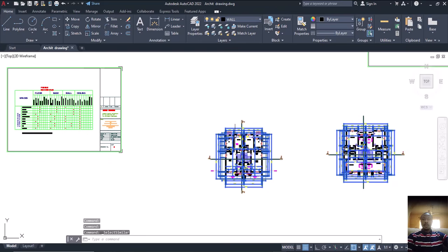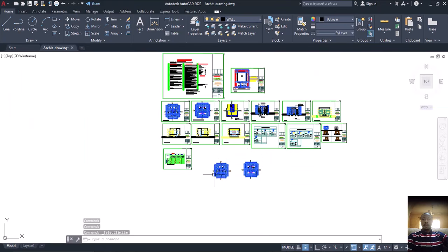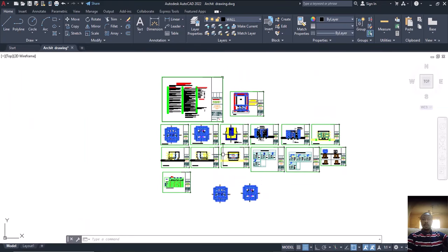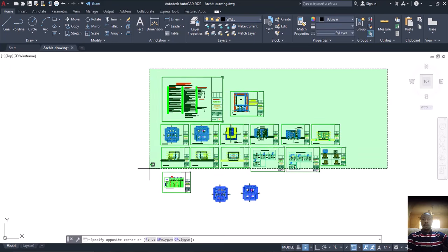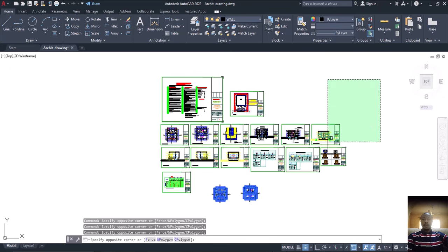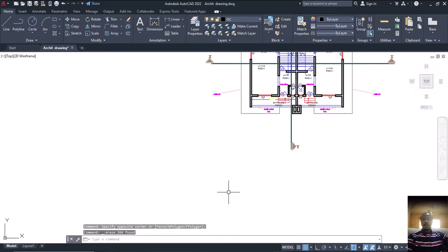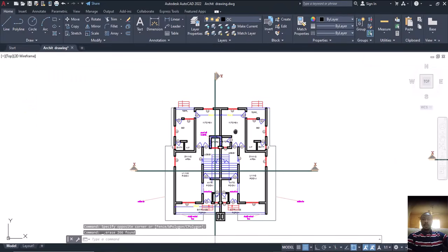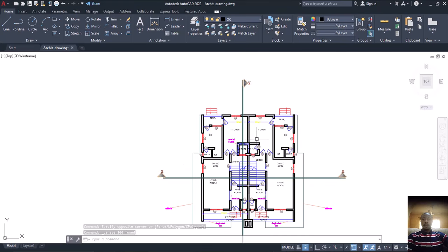And as I've said, anytime you click on select similar, make sure you check other drawings. Can you see? If you mistakenly delete any of them, automatically all of them will be deleted. So to avoid that, I'll press my shift key down and then highlight all like this, and then click somewhere here. Make sure that you deselect all of them. That's the reason why I'm doing it repeatedly. Then I will press delete. So as I have deleted it now, you can see that it's becoming clearer.